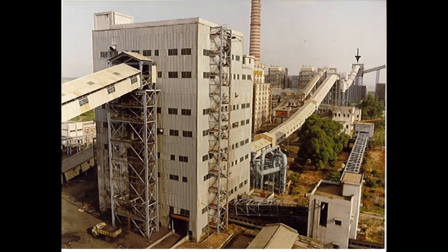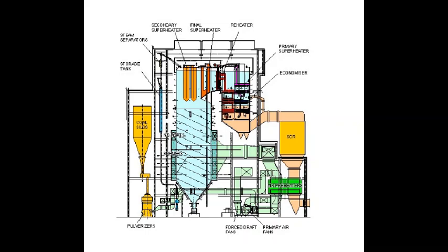The raw coal bunkers are placed in the vicinity of the boiler, and the coal stacked in these bunkers is stored in such a way that at least 2-3 days of coal feeding stock is available within these raw coal bunkers. There are individual raw coal bunkers for each of the pulverizing systems. That means each raw coal bunker is feeding a particular coal mill.